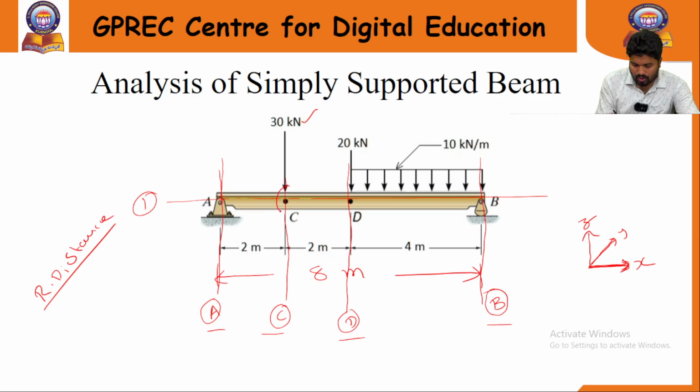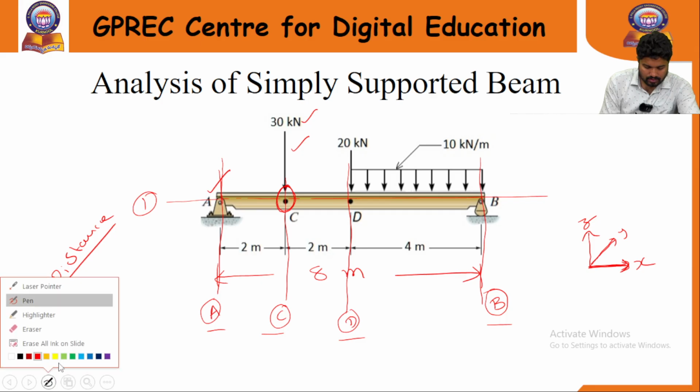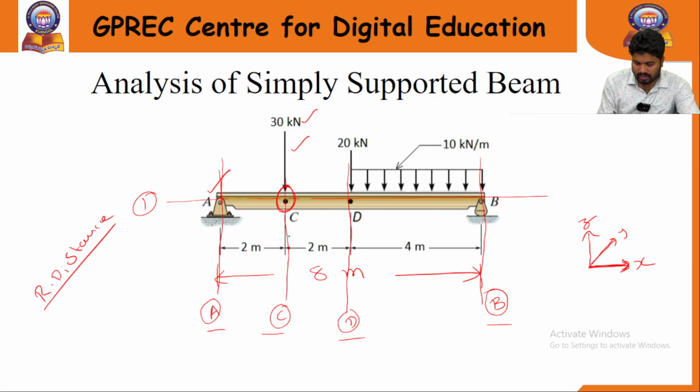If you want to apply the 30 kilonewton load at a distance of 2 meters from point A, in that case you need to give the relative distance. That means whatever distance this 30 kilonewton load is acting at, you need to consider it over the total length of the beam. What is the total length of the beam? 8 meters. So 2 in 8, a quarter of the distance. That means our relative distance is 0.25. By giving this 0.25, this 30 kilonewton load will be acting at point